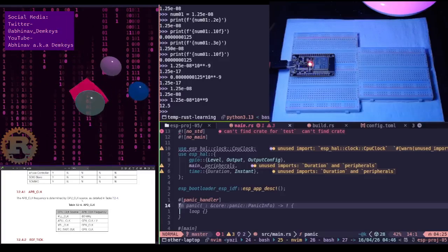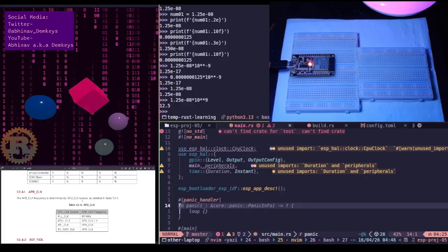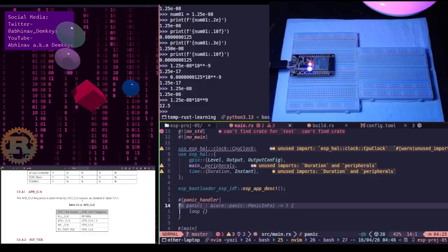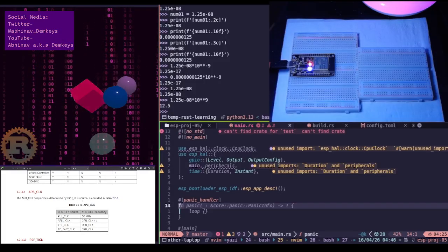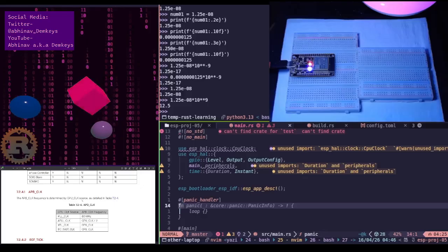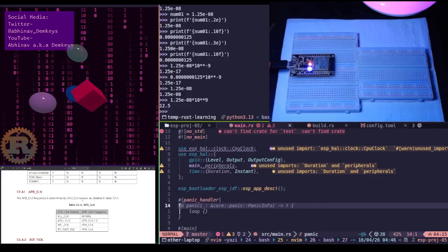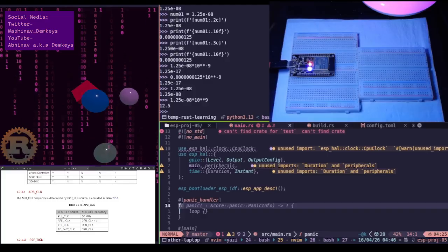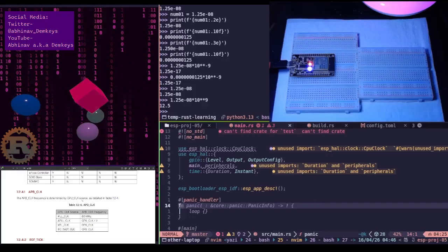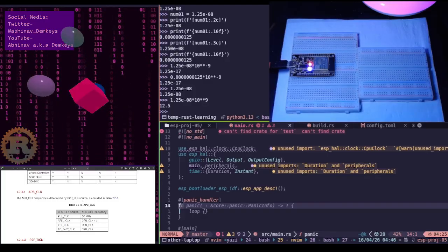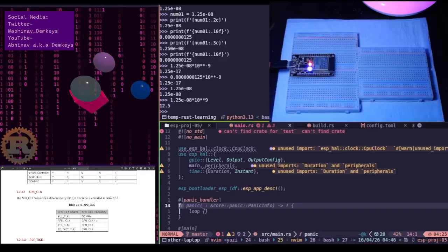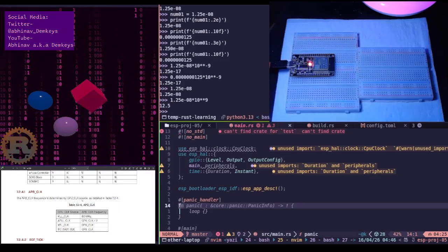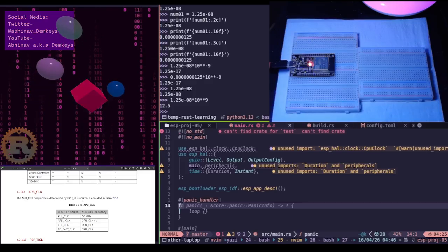That's the crystal oscillator generating a clock signal at 40 megahertz. This gets fed into the PLL clock, or the PLL. I guess the source is called the PLL clock, but the thing itself is called the PLL. So the PLL is going to take this XTAL clock signal and clock it up to 320 or 480 megahertz.